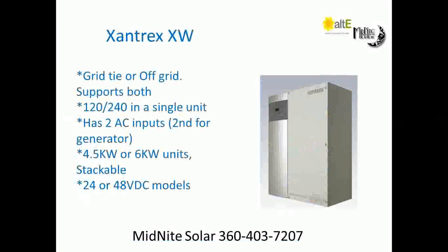I want to go back to AC coupling a little bit, and we'll probably talk about this more, but redundancy is usually good in this department. What I was mentioning earlier about having to disconnect the grid tie inverter when the batteries are full because they don't regulate in reverse. The Xantrex, however, is smart enough to know the batteries are getting full, and it does what they call frequency dithering.